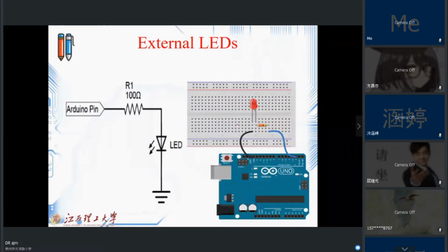This is the figure which shows how we can use, suppose, an LED on pin number 2. After the resistor, you put it here, and one pin, the anode one, you should connect to the Arduino board, as the figure here shows.